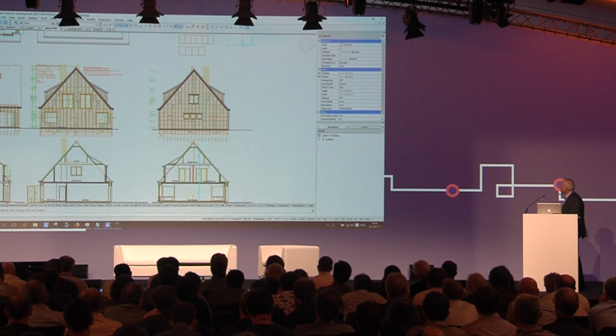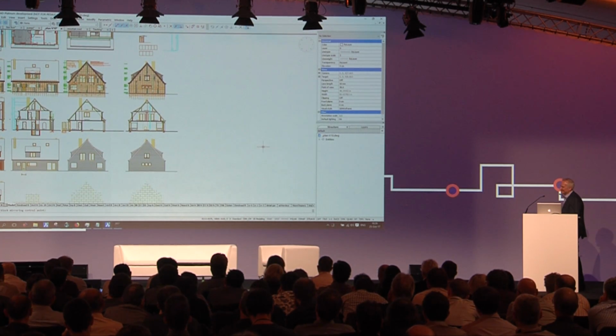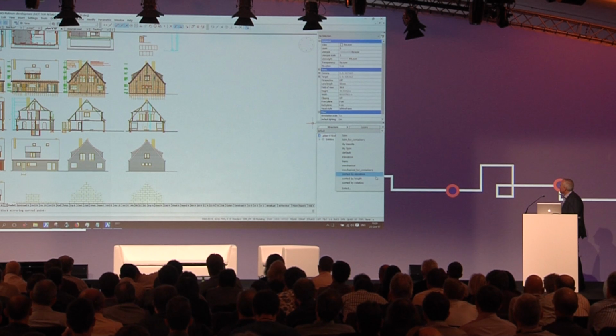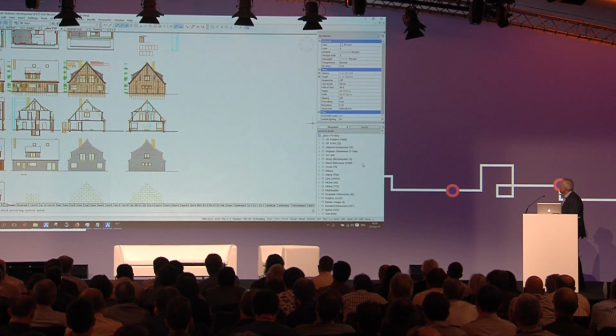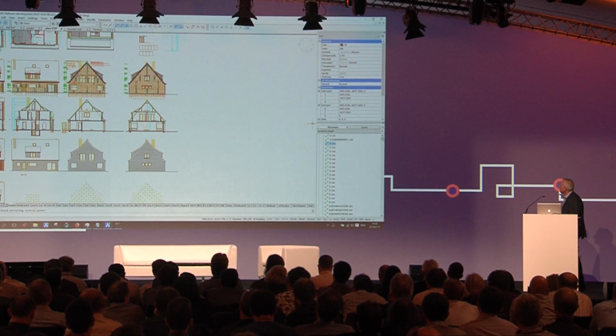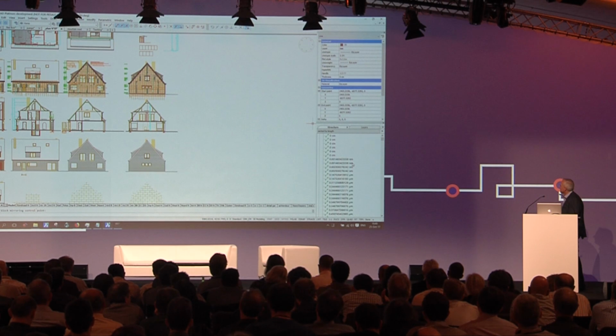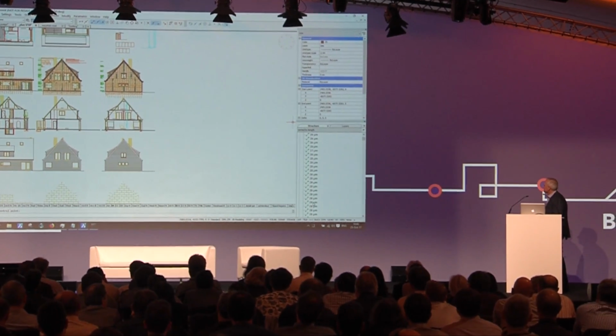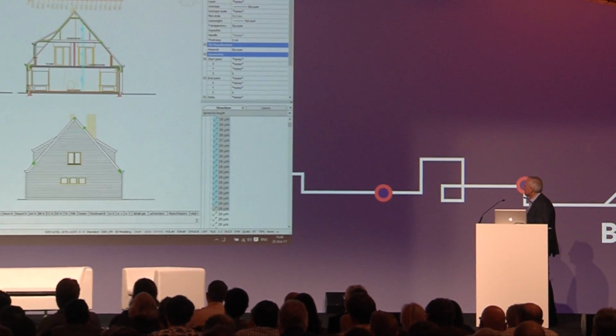Some drawings look clean at first sight, and then there are things that you don't feel comfortable with, and you want to check. So let's sort the entities in this drawing by length. And why would I want to do that? Well, if I look here, you see all these entities that have 0 length, 0 centimeters, or 0.01 nanometers, and micrometers. All that stuff, I bet it's garbage. So I just select the whole range of it, and they all get selected in my drawing.